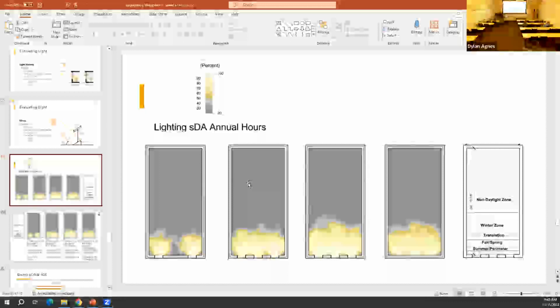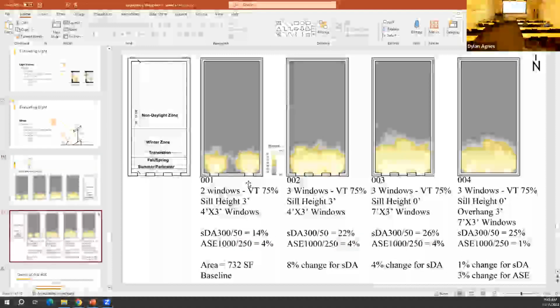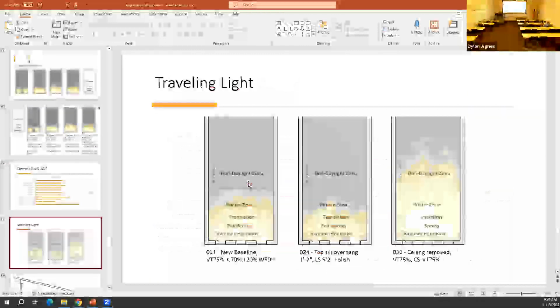And so then you can take the actual daylight simulation itself and plot it with that, and give out the variables and the numbers, statistics, what you changed, how it impacted the design, etc. This is what I like to do if I have time on a project: I'll do the daylight simulation and then I'll draw the IECC daylight harvesting zone, and I'll literally overlay it and prove this is why it's not the best measurement.